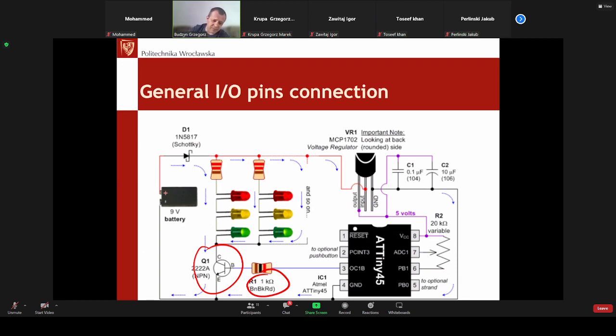Of course, there is a series resistor in order to limit the current flowing through the diodes, because depending on the voltage at this point, it would be possible to burn the LEDs. With the series resistor, it's not. Then we can regulate the brightness of the LEDs and protect them against overcharge and against breaking down.